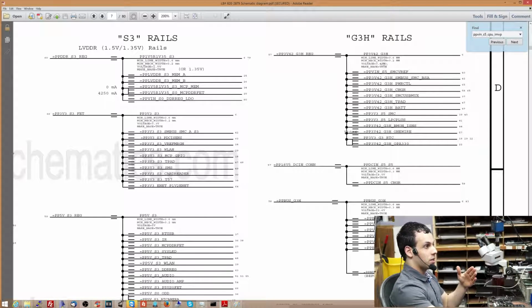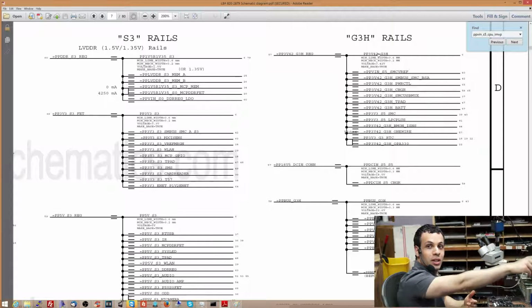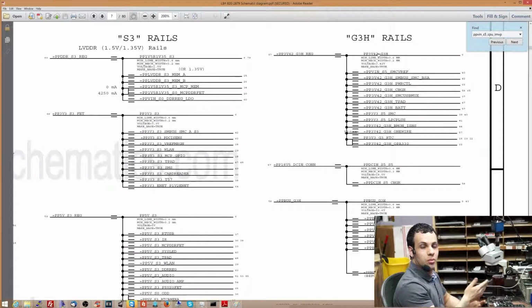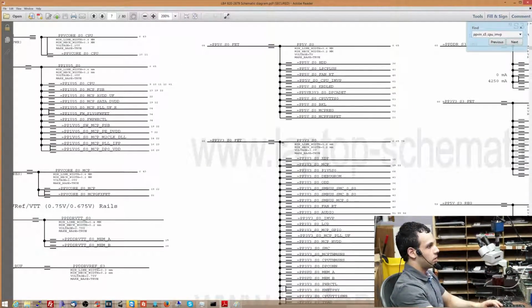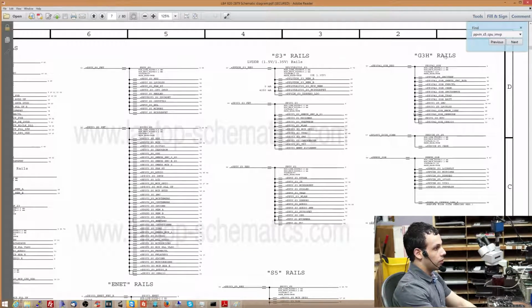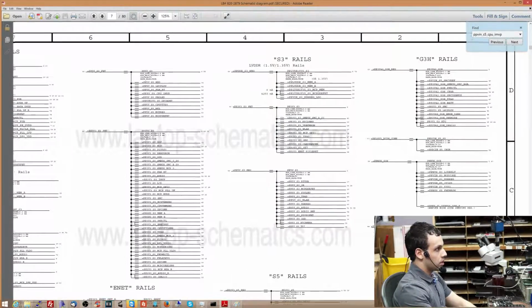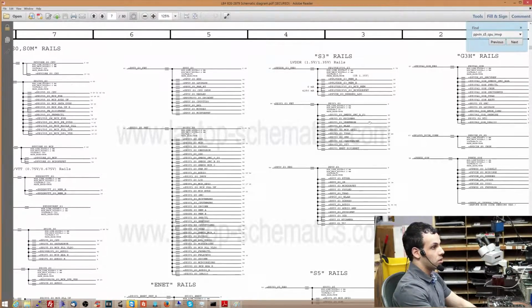And even if you don't have it saying voltage 3.42, if you measure it on a good board and you see that there's 3.42 there, and you see that the schematic calls it PP3V42, eventually it should click that that's a 3.42 volt power rail. So this is pretty much power rails. They're just different rails of power. I know you're not supposed to use the word to describe the word, but it really is that simple. It's just a list of all the voltages that are needed for the computer to do different things, and if some of them are missing when they're supposed to be there, then you know that's the part of the circuit that you start troubleshooting.